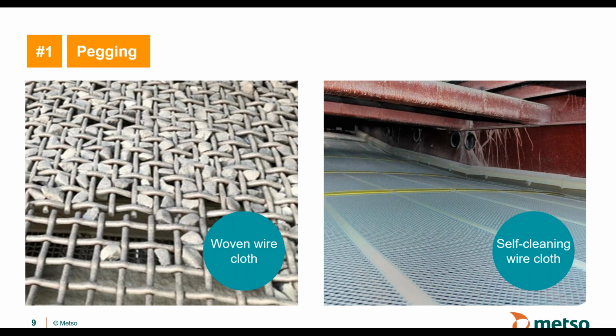Other differences between these two cases is also the fact that the left-hand cloth can carry a higher material bed because it's stronger and more stiff, while the one to the right may have limitation in terms of what bed depth you can carry over the deck, because the wires may eventually split apart from each other and release rocks bigger than intended through the deck. So let's continue.